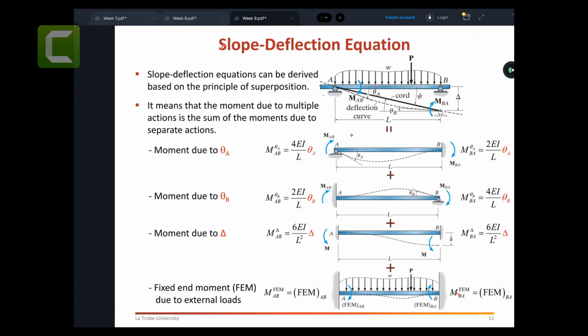What are we going to do? Let's release one of the clamps and get the theta A to release. Right, so let's allow 1 degree of kinematic indeterminacy. So can you please tell me the kinematic degree of indeterminacy for these ones? You tell me kinematic dk equal to 0 here. So that's all good. And the dk for this structure is 3.